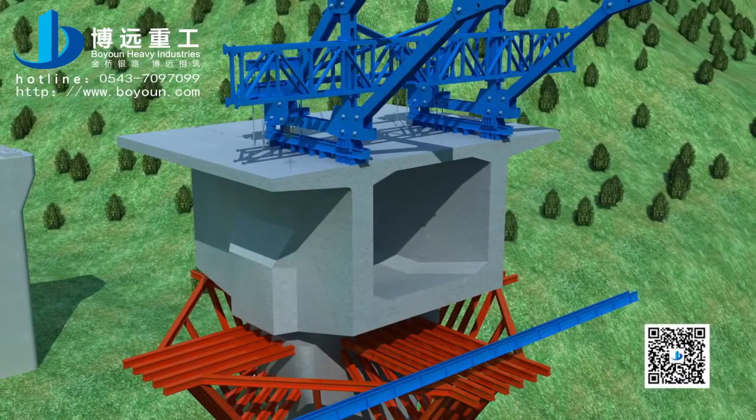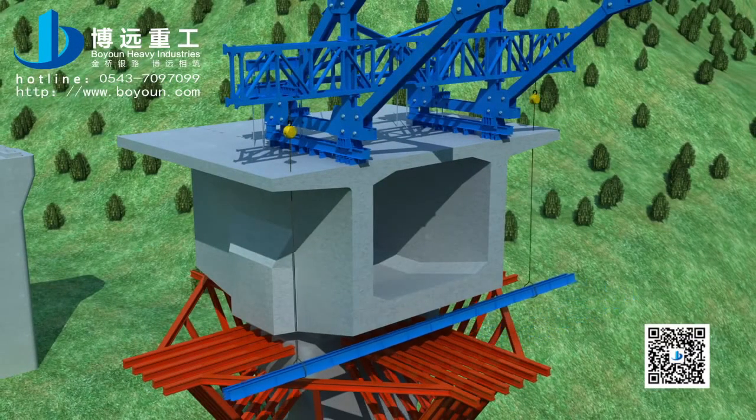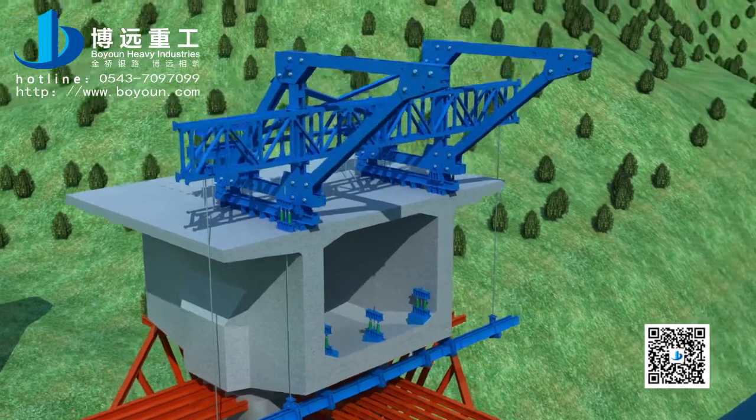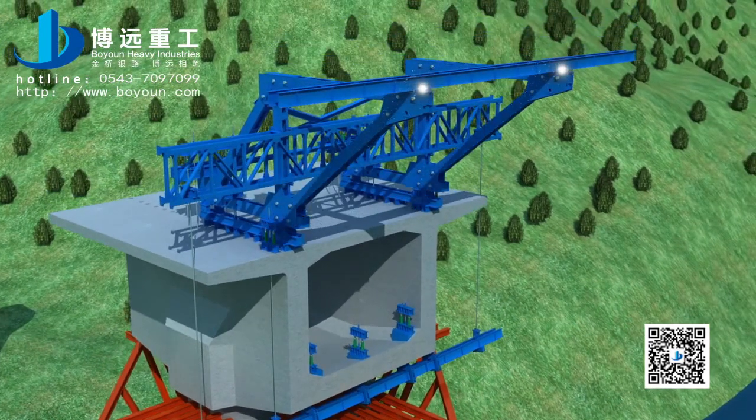Install the rear joist through the bottom formwork reserved hole, hanging the rear joist in place by hangover rod and hangover frame at top and bottom to connect and fix. Install the front upper cross girder, weld and connect to the diamond frame. Install carrying pole beam and hanger rod.